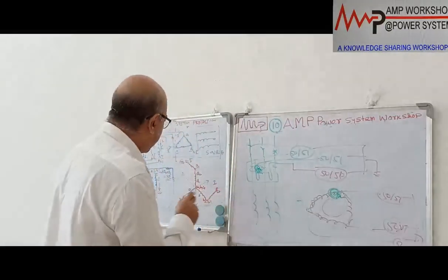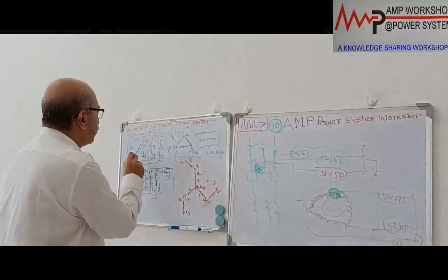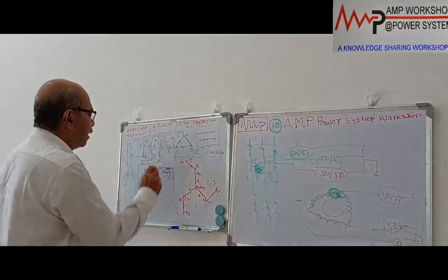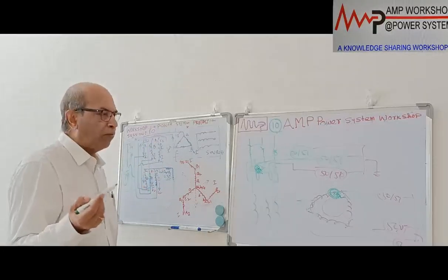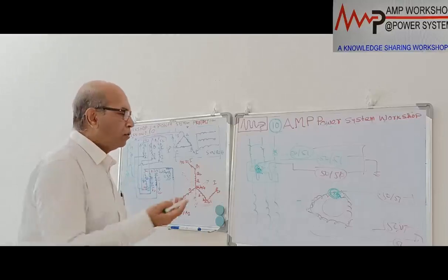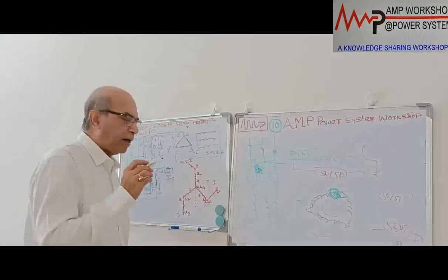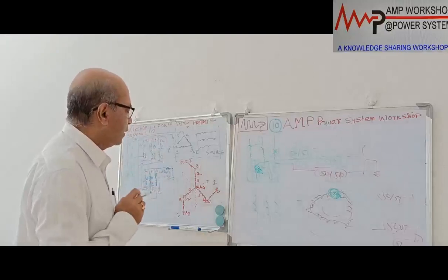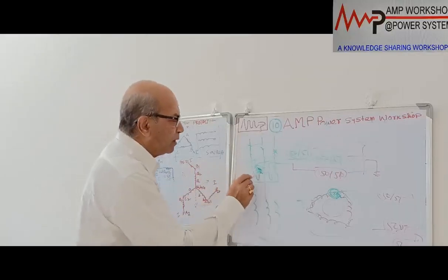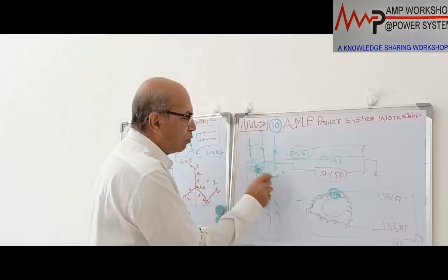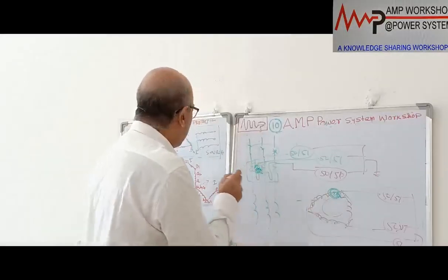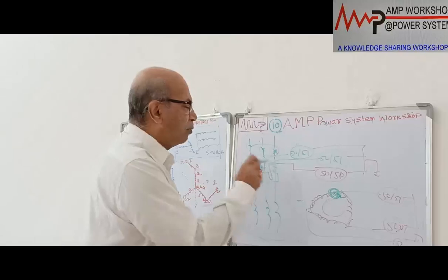So the arc fault current flowing through this will be disconnected. It will be tripped from here, so no arc fault current will flow. Then the motor can operate normally and wait for the next arc fault, working for that time period. So this is the purpose of this delta connection. With the closed delta connection arrangement, we can detect the external arc fault.